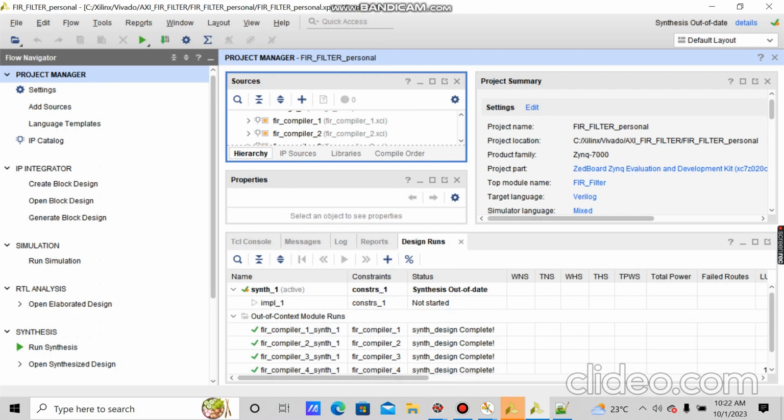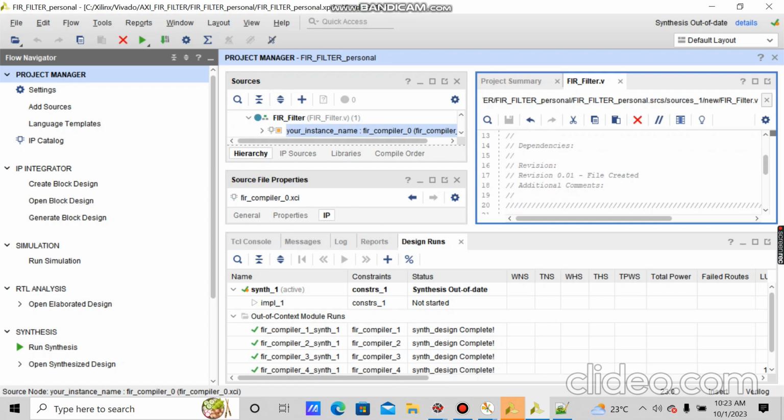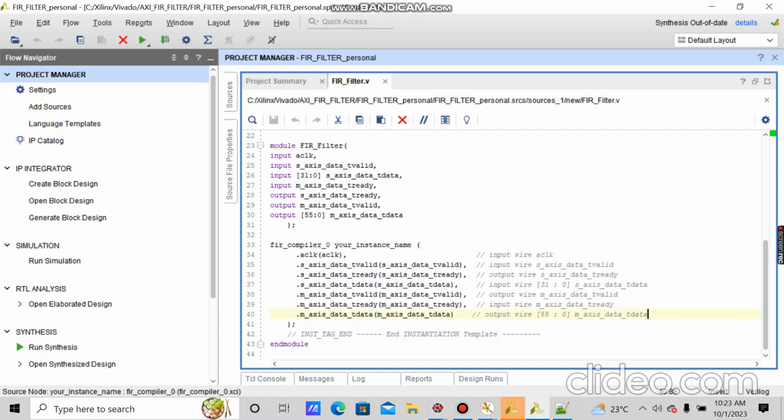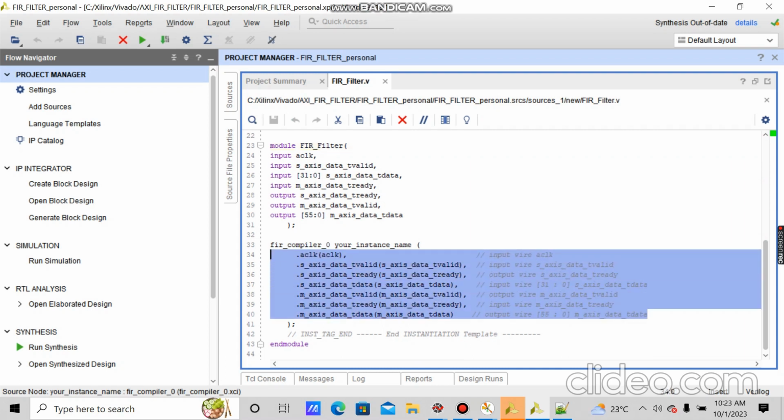In Vivado, there is a certain flow which I will tell you later, but we have 2 files, like a FIR filter.v file, which you have to instantiate. There are some instantiations here which you can do, and map your FIR filter variable to an IP which Xilinx provides for doing all the computation for the FIR filter. You just have to give the input, that is the coefficients, and your input signal in terms of binary. You can give decimal also, but binary is preferred.